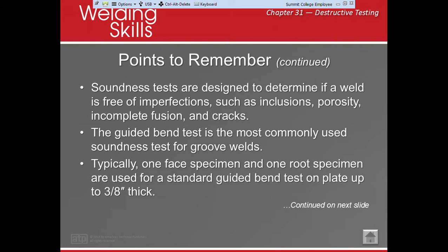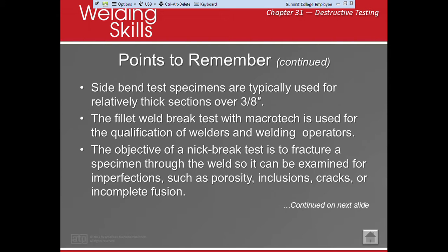The guided bend test is the most commonly used soundness test for groove welds. Remember that. Typically, one face specimen and one root specimen is used for a standard guided bend test up to 3/8 of an inch. Okay? Now, if we're doing an inch thick, we're going to use side bends.